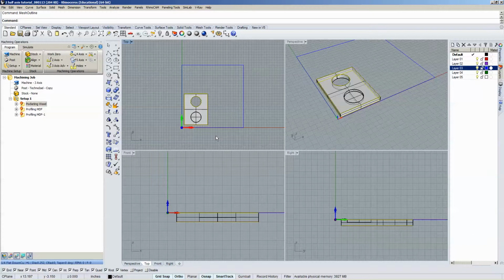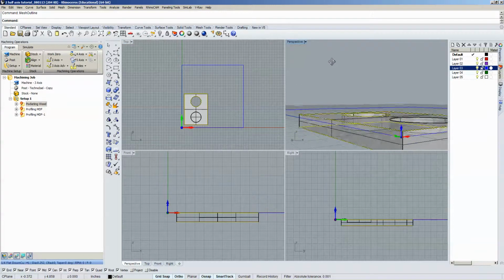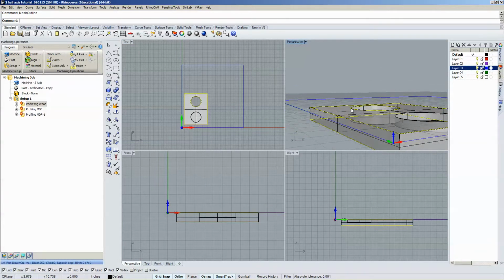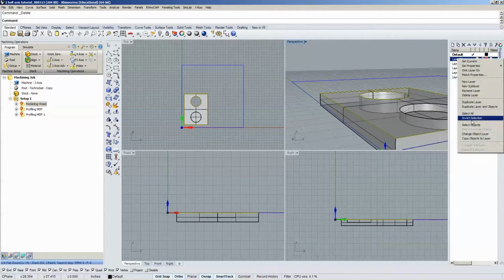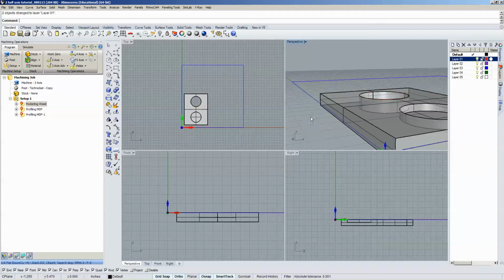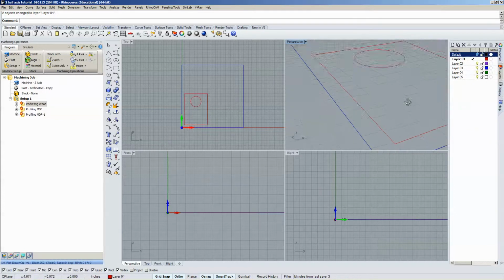If I didn't retain my curves, and I'm looking at this, I'm seeing that this curve and that curve are at the z equals 0 plane, and I want those, but I don't want this bottom one. All right, so select this, and that, and just to keep track of it, I'm going to change the objects layer. Okay, so right now we have 2 curves.